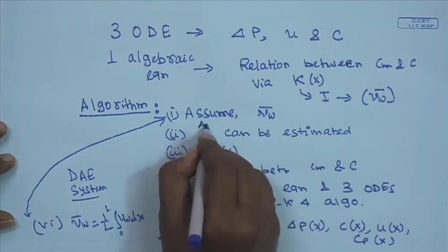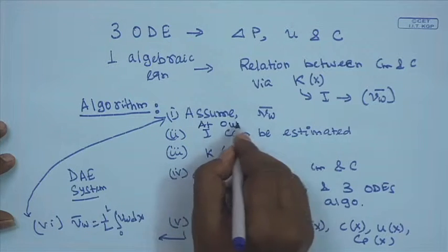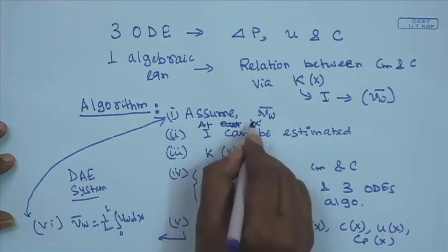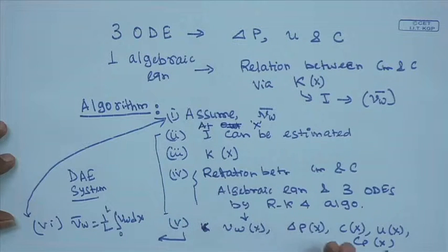So, Runge-Kutta 4 nested with the Newton-Raphson method at every step of RK4, and then there will be an outer loop which will be carried out at a particular value of x. This will be continued till it goes for the full length of the channel at a particular x. So, this whole calculation has to be done at a particular value of x, and then we have to go forward to x plus delta x if it is converged, and likewise we have to do the calculations at every x location.